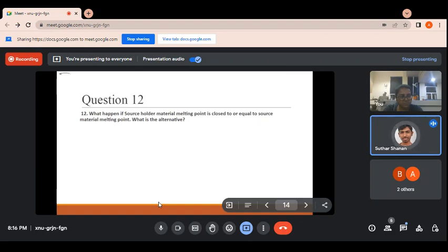But in week 8, there is an assignment question regarding the SU8 procedure, the order of the procedure. In that order, they mentioned first soft bake. This one is right. Then here they mentioned UV exposure. But if you watch the week 4 video, UV exposure comes after hard bake. But in the week 8 assignment question, it is soft bake, then UV exposure, and only after that hard bake. So both are SU8. In week 4 it is the same SU8, and week 8 is also the same.